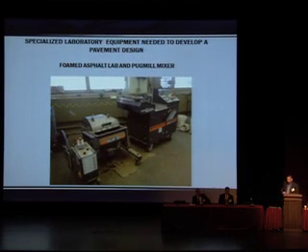So once you know your active filler, once you know your water rate and your bitumen and everything else, you can move on to actual pavement design. This is a shot of the foamed asphalt lab pug mill mixer that they have at TTI. Pretty expensive piece of equipment. As far as I know, it's the only one in the state.